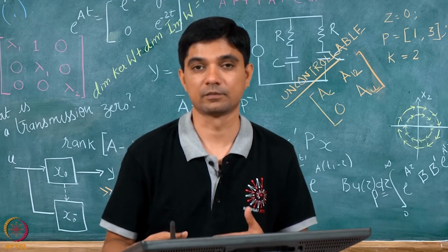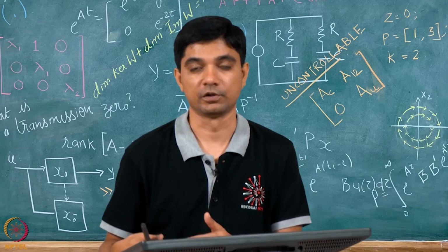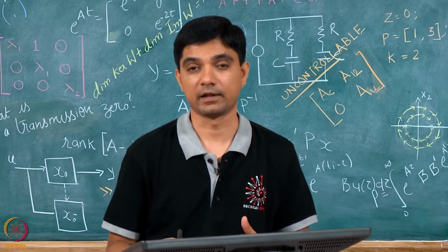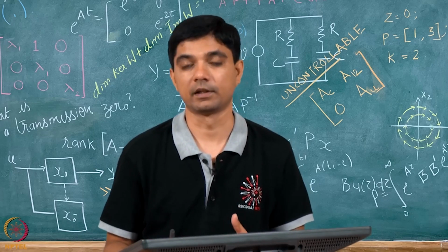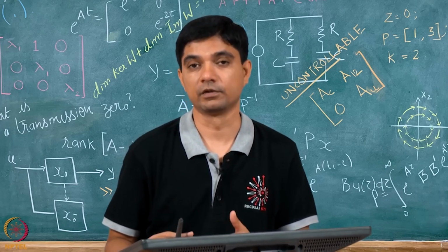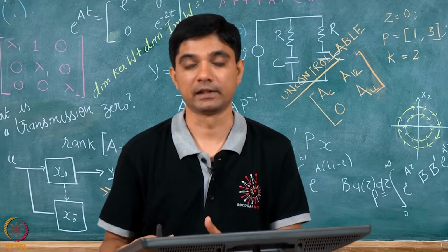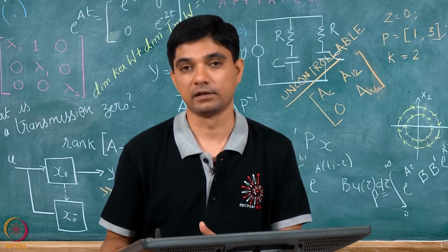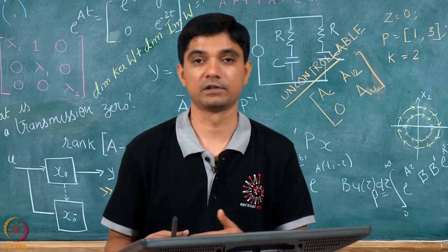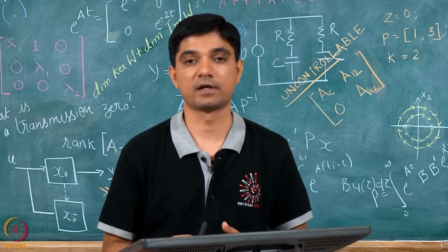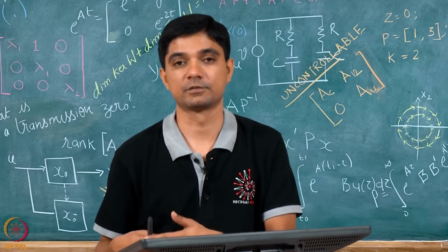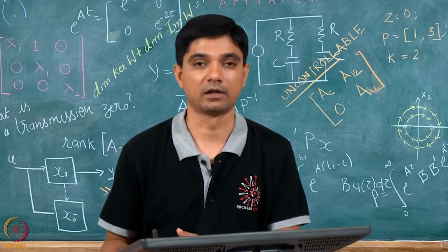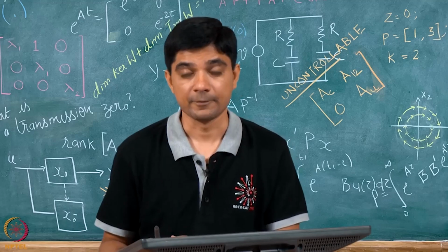So last lecture we had defined for ourselves a few concepts of stability, starting with just the notion of a stable system where the solutions were uniformly bounded. Then you had the notion of asymptotic stability, which did not tell me about the rate of convergence of my solution to the equilibrium point. And then we had the exponential stability notion, which had some information on how fast my solution approaches the origin. And of course, the systems which are not stable are unstable systems.